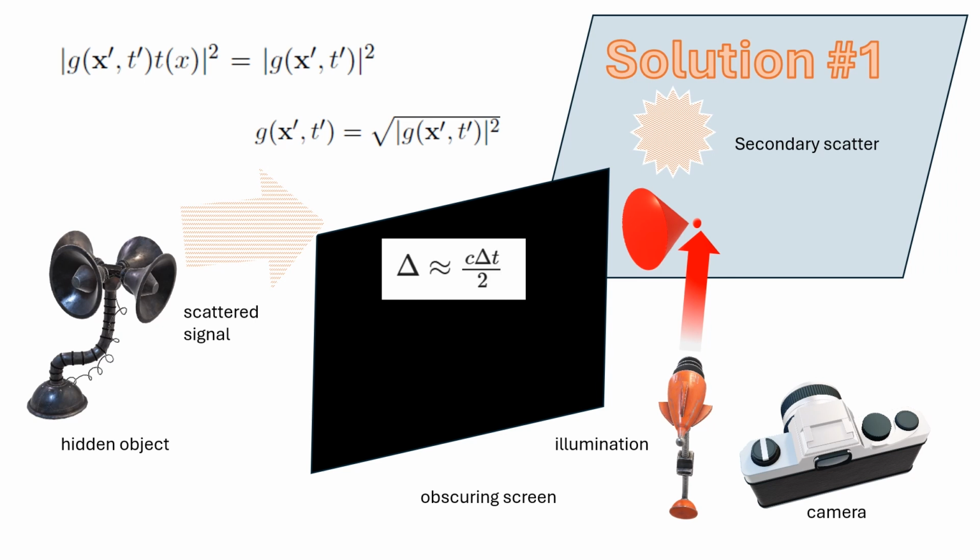The resolution in this case is going to be proportional to the temporal width of the signal, because basically we're using the pulse to measure time delay at various points on the object. So if, for example, we had a nanosecond pulse, then you'd have about a 25 centimeter, a quarter meter kind of spatial resolution. If you go down to a picosecond pulse, you could get down to a millimeter scale resolution. But you're limited by this overall time delay, and you're limited in the complexity of the object because you've essentially made this assumption that the object is a positive valued scatterer.